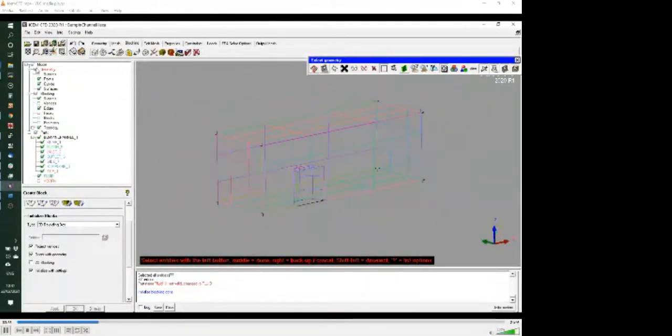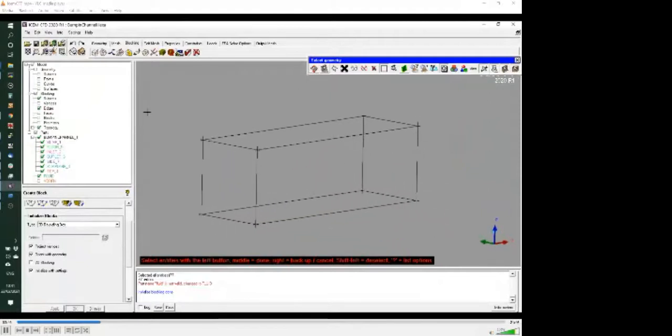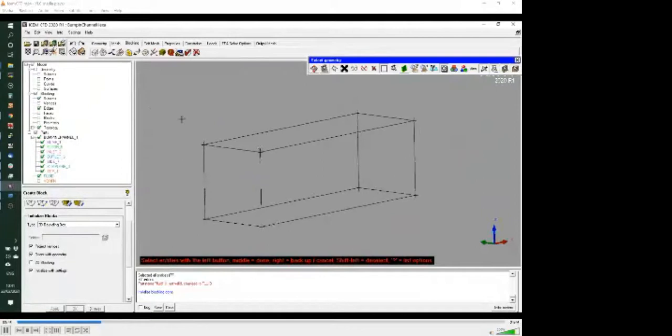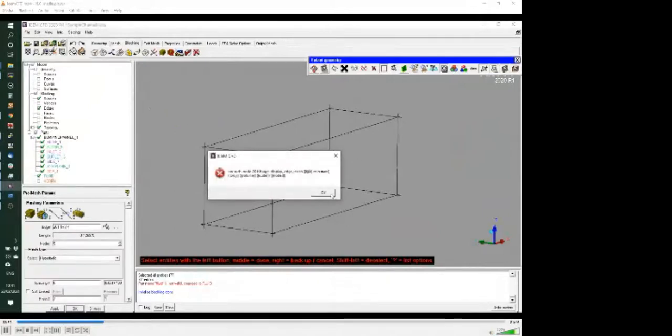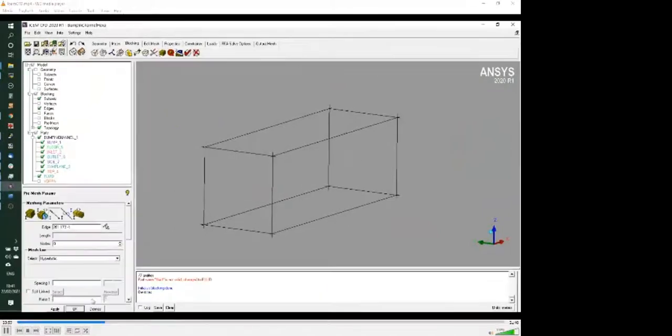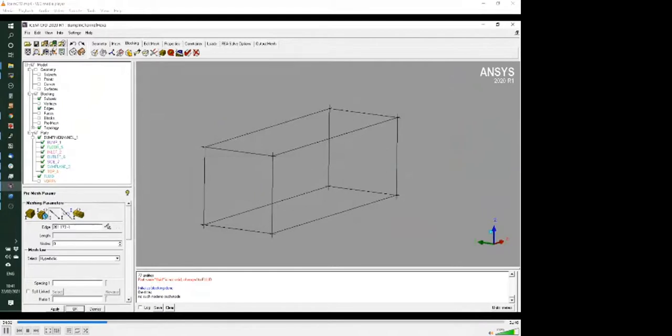We can switch off the geometrical representation so we can see what the mesh block looks like. It's very simple at this stage. There's nothing to it. It's a purely prismatic block. There's always some nasty error messages in the software. Best just to continue, dismiss everything we've seen up to this point. We can now assign grid spacing on each edge.